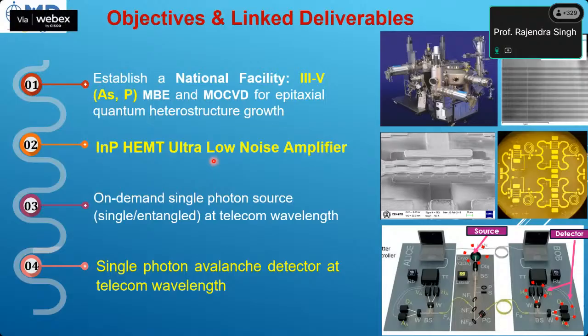And then surrounding that, there will be RF signals, and these RF signals will be amplified by the low noise amplifier, which will be sitting at 4 Kelvin ambience. So there is a qubit which is sitting at tens of millikelvin, and there is a HEMT-based pre-amplifier which is sitting at 4 Kelvin. And these have to be ultra low noise amplifiers.